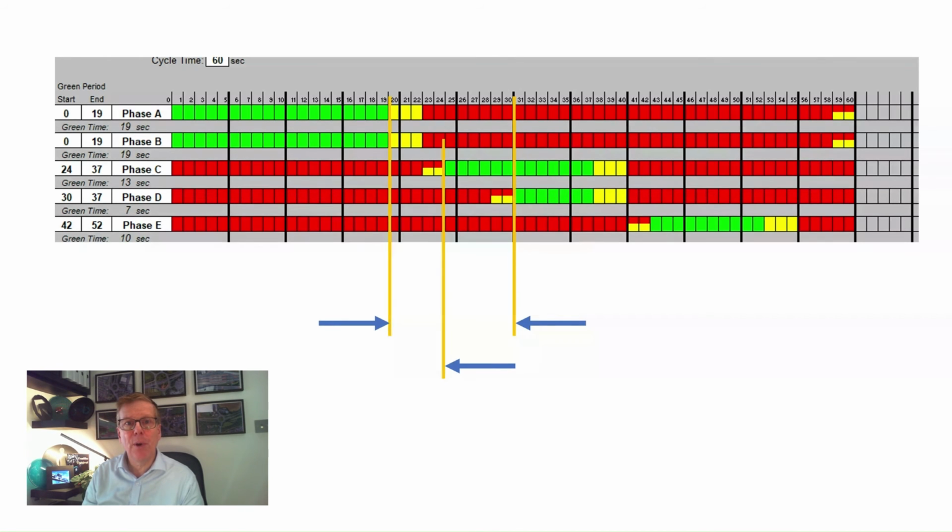Phase delays can be used for both phases losing or gaining right-of-way. The phase delay is specified on a particular stage-to-stage movement, so it doesn't have to operate on all movements to or from the associated phase. Typical uses include extending a phase green period to increase traffic throughput, or to delay a phase starting to allow an opposing phase to establish itself to block right-turning traffic at the start of a stage.